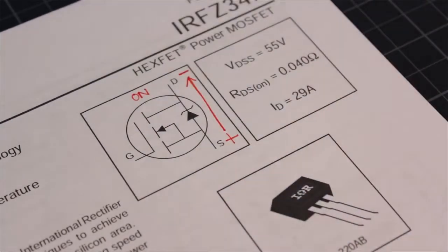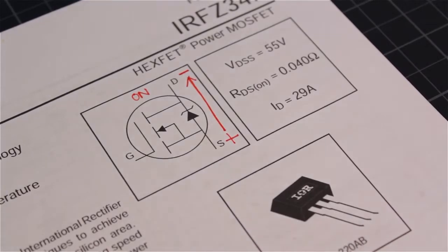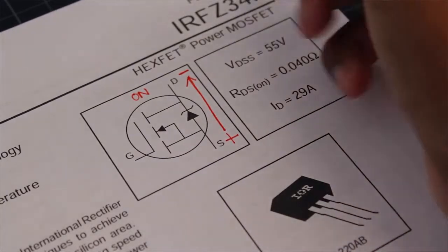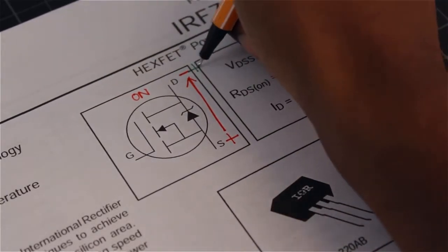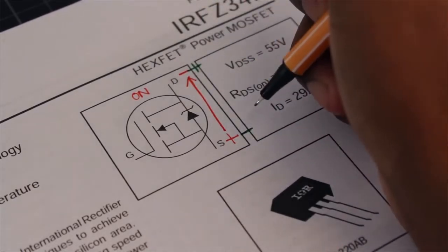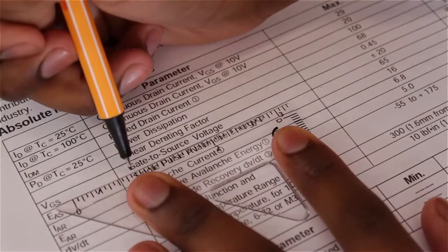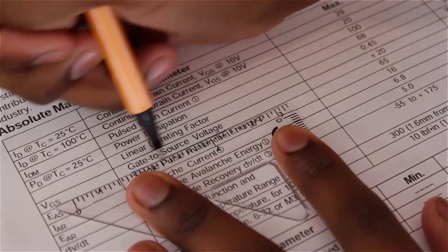This means that our MOSFET will always be on, regardless of the control voltage we put at the gate. The whole point of a transistor is to be able to control the voltage, so you always want to put your higher voltage at the drain and the lower one at the source for a MOSFET, but we'll talk more about this later.